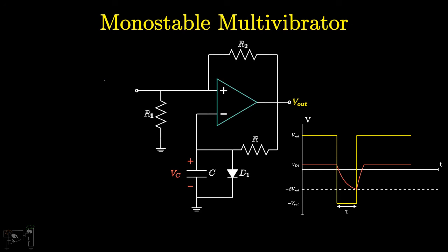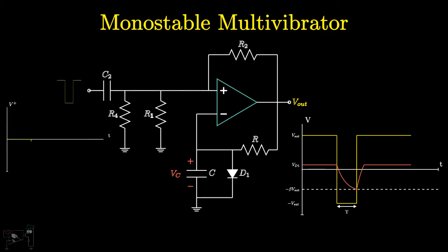We want the input trigger to be as short as possible. Hence, an RC differentiator is used to get a sharp trigger. Further, we want only the negative trigger edge. Hence, a diode is added in the path to extract only the sharp negative trigger. Hence, we have built a pulse generator.